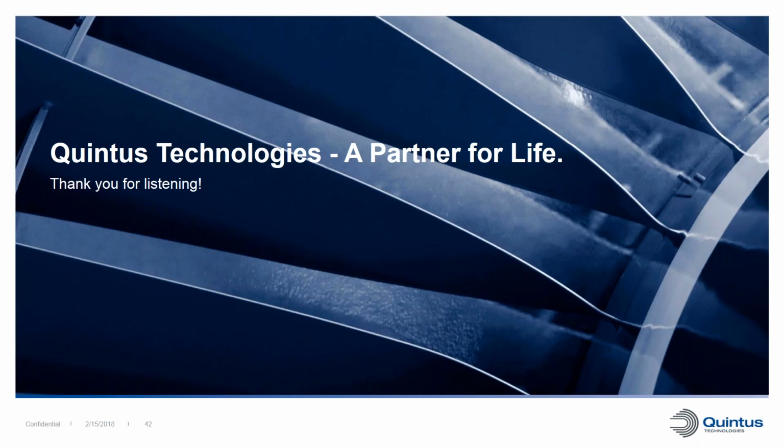Okay, the next question is from Larry. Can you include post-processing like heat treatment into a Quintus HIP? Yes, we talked a little bit about that. We'll talk about that much more in the second webinar. But yes, you can, all kinds of heat treatments. It's a very flexible system. We can heat, we can cool with different rates, we can have different hold steps, and we can add infinitely many steps to the cycle.